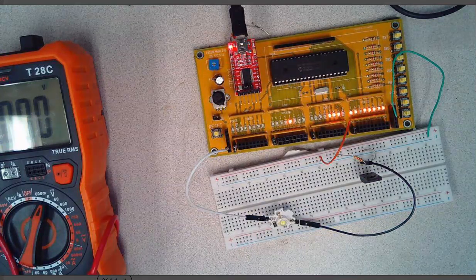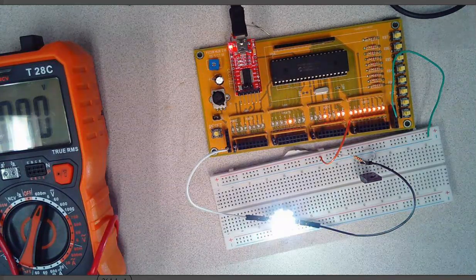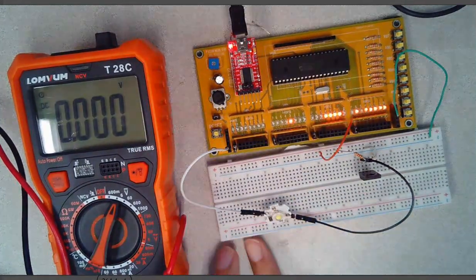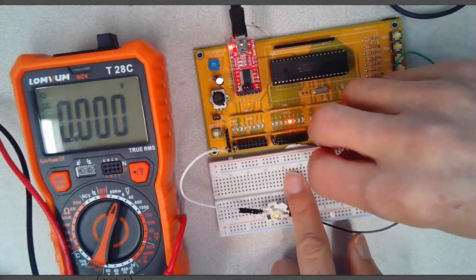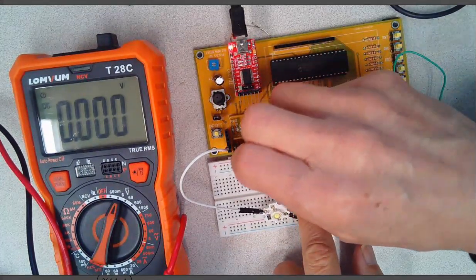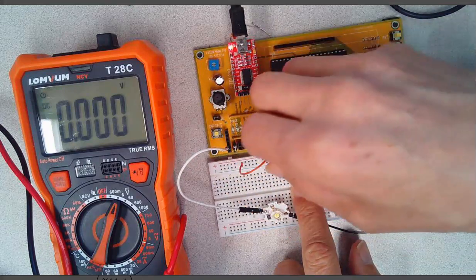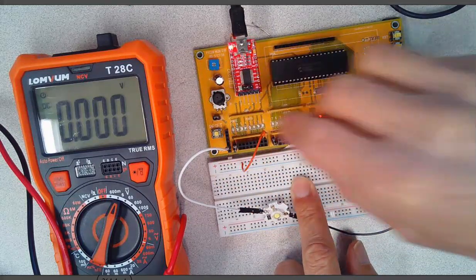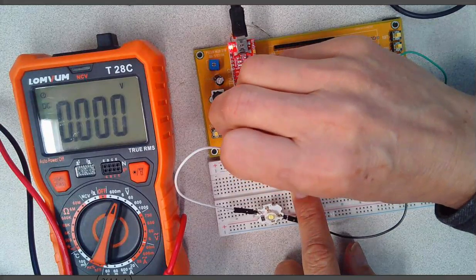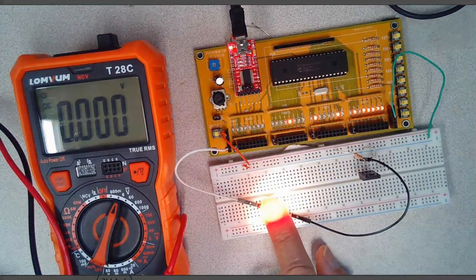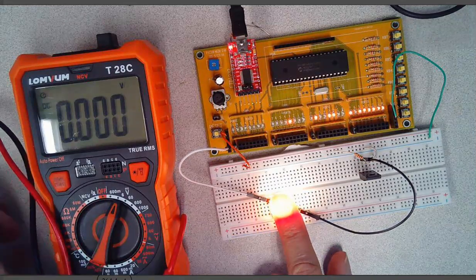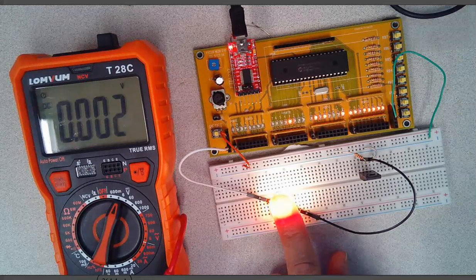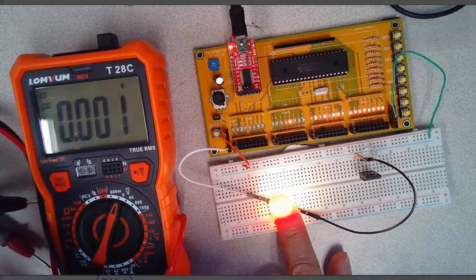Now I've got power, a really bright light. That's what transistors are for. They crank up the power. If I want to find out how the LED behaves, the thing's really bright, I will take the base resistor right here, take it straight to power. That turns the LED on all the time. It's really, really bright. Measure the voltage drop across the LED again. Measure the voltage across the 6.8 ohm resistor.